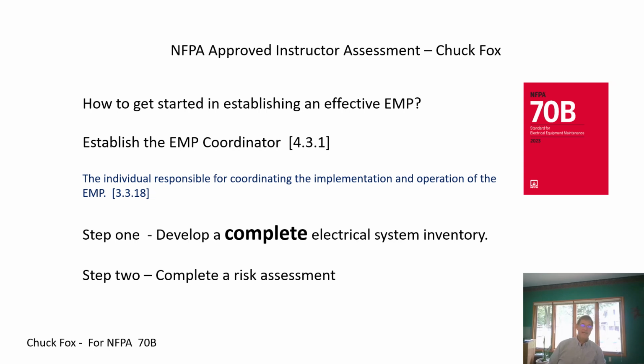So my topic for today is how to get started with an electrical maintenance program. And typically that is a question that has a lot of parallels to how to get started with an arc flash risk assessment, which has been a challenge of developing that throughout the years. The first order of business, of course, would be to establish the electrical maintenance program coordinator, and that's specified under Article 4.3.1. So the EMP coordinator ultimately is the individual responsible for coordinating the overall implementation and operation and ongoing success of the electrical maintenance program.